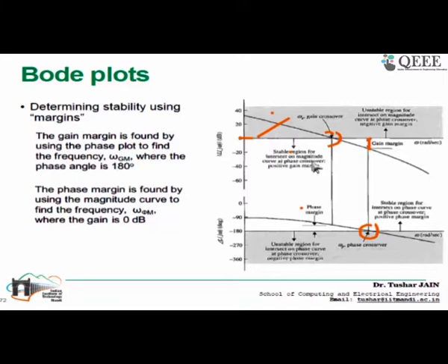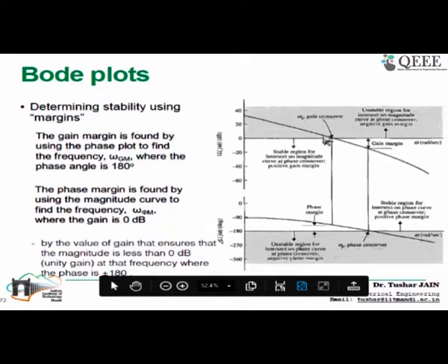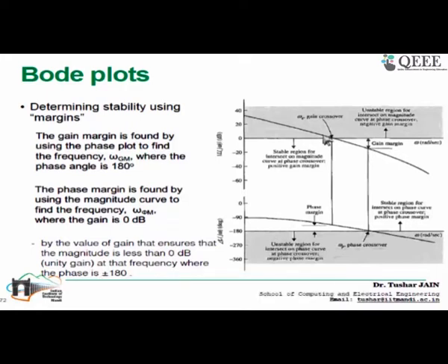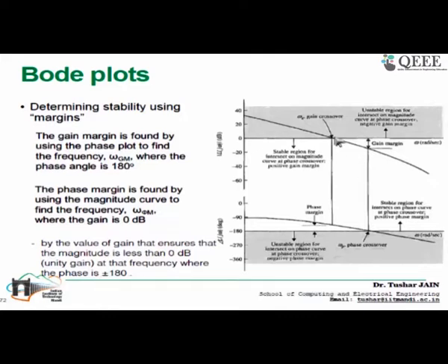And what flexibility it also gives you, we will see in the next couple of slides possibly. So the idea is you plot the Bode plot using the transfer function given to you, and then you compute the phase margin, gain margin, and these two crossover frequencies. For this you do not need to first plot the response. You can also do the mathematical calculations: at what value your function of frequency crosses the minus 180 degree line, and similarly, for your magnitude response, at what frequency it crosses the 0 dB line. And at those frequencies, you can compute your margin. It's not really necessary to draw the Bode plot, though once you have a plot, it gives you more visualization.